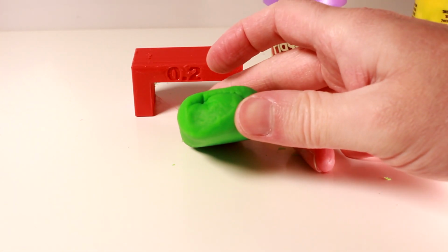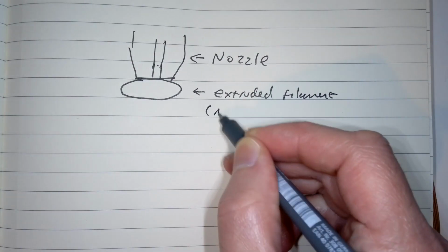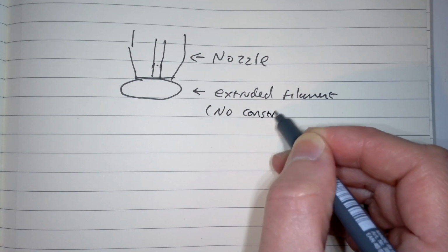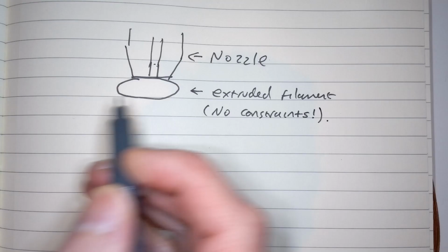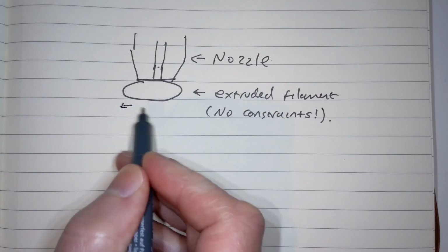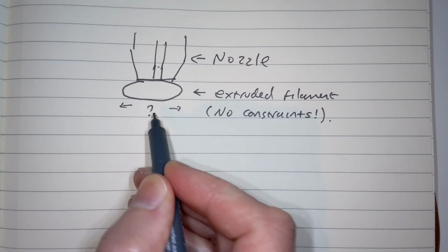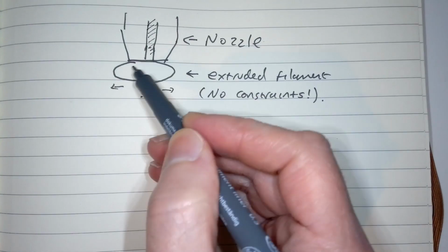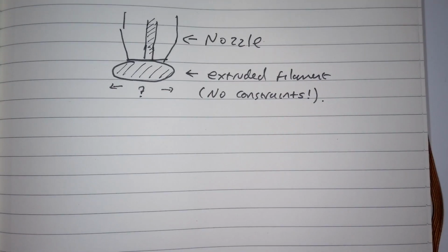The height we specified in the slicer is therefore just the height of the nozzle above the existing lower structure or the bed. The height is pretty reliable so long as the printer is working correctly. The width, however, is a dependent variable in this case, dependent on, I suppose, the viscosity of the molten PLA, in combination with the line height and the amount extruded. The short answer is it will form this shape, and so the width is kind of, I guess, approximate.